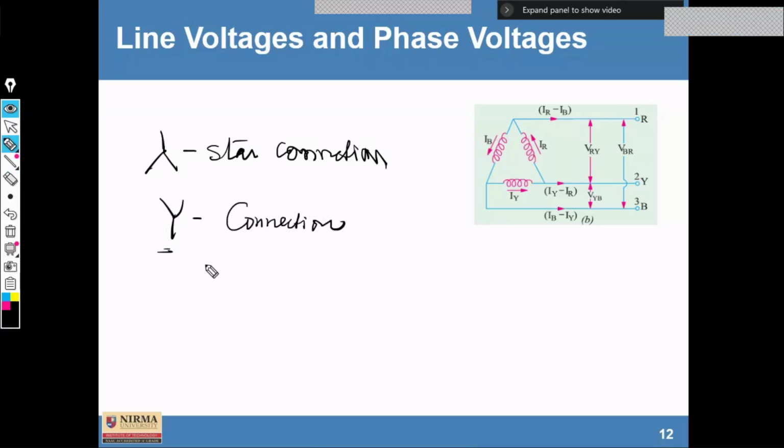So if it is asked in examinations as Y connection, don't be afraid of it. Clear? Y connection is a star connection. Okay, and for star connections, looking at this, you simply have to remember one relationship, the line current and the current flowing through the phase, that is the phase current. So if you draw this figure on your rough page, you can easily write the four different relationships.